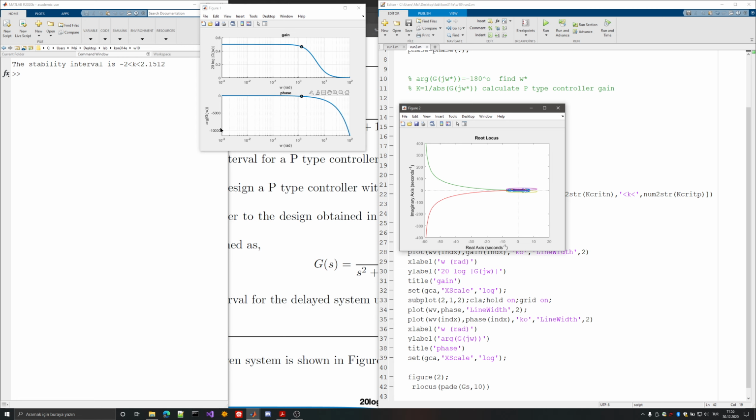And you can see now, adding delay to the system affects your stability dramatically, because it will subtract an amount that depends on the omega value and the amount of delay, so tau times omega. So it is really important to note that if you have a high delay, then in high frequencies you might have been lost, because it tends to minus infinity. So since we are only interested in 180 degrees, the higher the delay, the lower the upper bound for stability using a p-type controller.